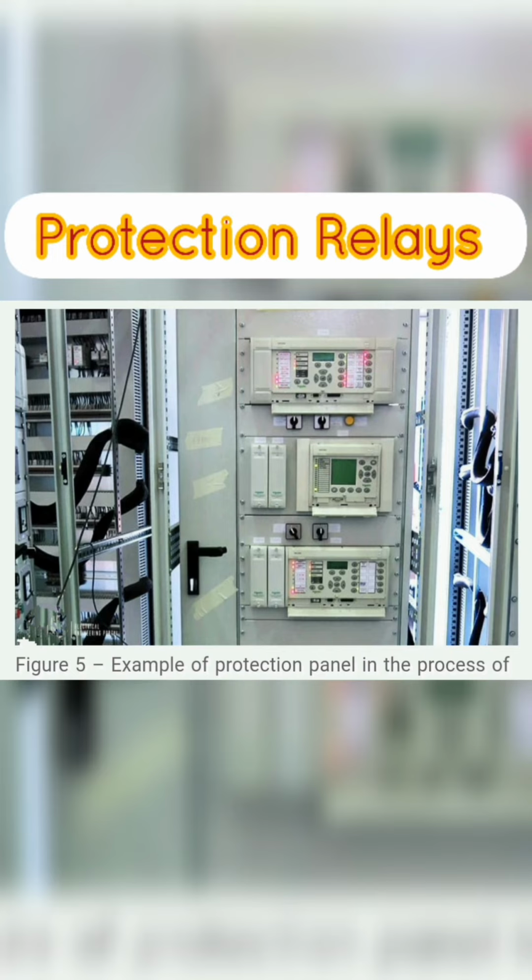Next we learn about protection relays. The function of protective relays in a substation is to cause the prompt removal from service of any element of a power system when it suffers a short circuit, or when it starts to operate in any abnormal manner that might cause damage or otherwise interfere with the effective operation of the rest of the system.